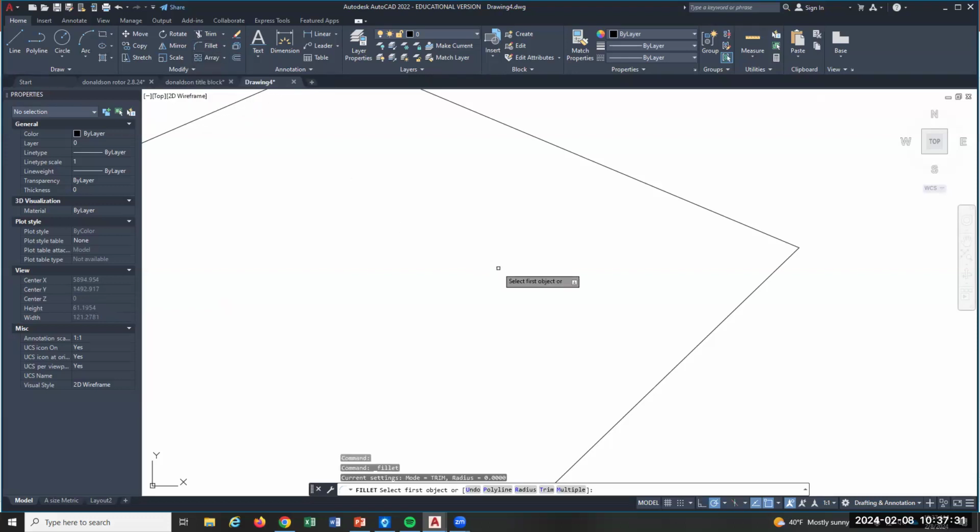The really weird thing about fillet is its default radius is 0. So you're gonna be using fillet and going, it's not working. It's like, oh, you didn't set your radius because the default radius is 0. I think that's dumb, but so if I go here and here, nothing happens. How come? Yeah, the default radius is 0. That doesn't help us really, AutoCAD.